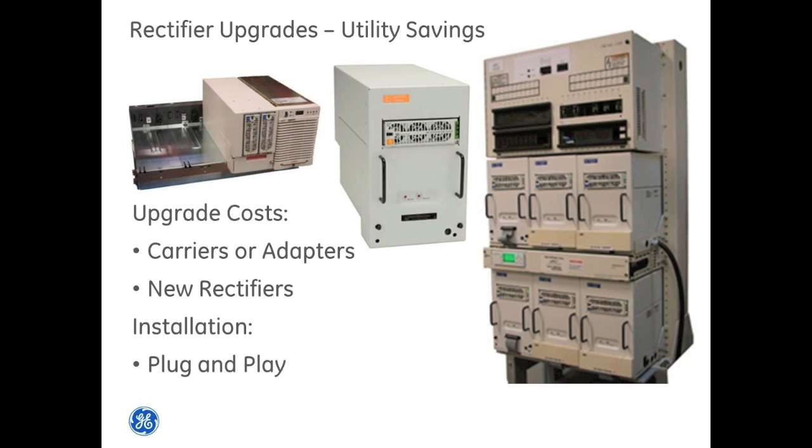So the ability to unplug the old rectifiers and plug in a new, more efficient one is clearly a significant cost savings in terms of the installation costs. And the way we've done that in several cases is take one of the new rectifiers and put it into a carrier or adapter, and that allows you to plug the new rectifier into the older system.